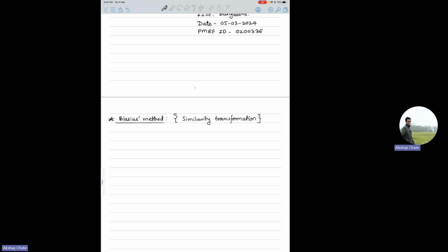I think he was a PhD scholar a long time ago, working on this boundary layer problem. He conducted a couple of experiments, and he plotted a curve where on the x-axis you take u divided by u infinity. u is the velocity at any particular location in the boundary layer, and at that particular x, you plot the u by u infinity ratio against y by delta.